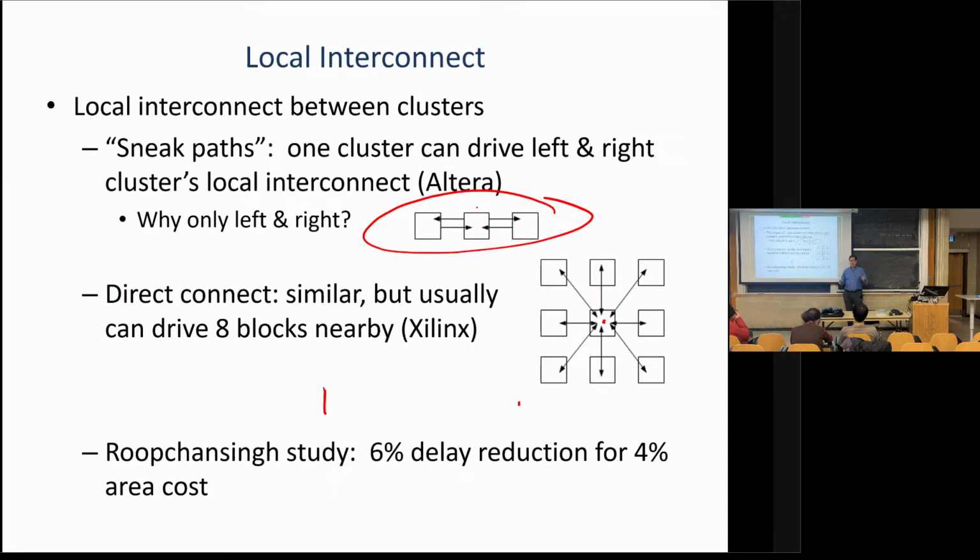You can go up to about 2 to 1 before the CAD tool starts, you notice significant effects, and it just can't fix it enough, so you need to add more routing. But up to about 2 to 1, it's almost area neutral, right? It would be best to make them exactly the same, but it's not much different. And because the horizontal is cheaper, that's what Altera does. That's part of what tends to make the logic block asymmetric, right?